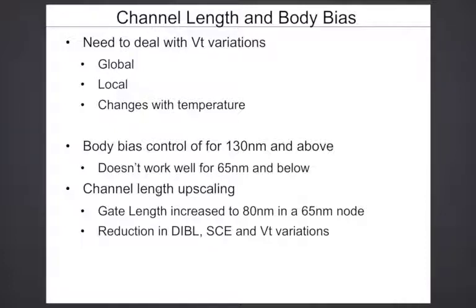So increasing the channel length, of course, what it does is, whenever you increase the channel length or the channel width or the product of the two, the area goes up, and as the area goes up, the variations come down. But you have to do it in a careful way, because if you increase the area, variations come down, but the capacitance goes up, so the dynamic energy can go up. So you have to do it in a very careful, calibrated way.